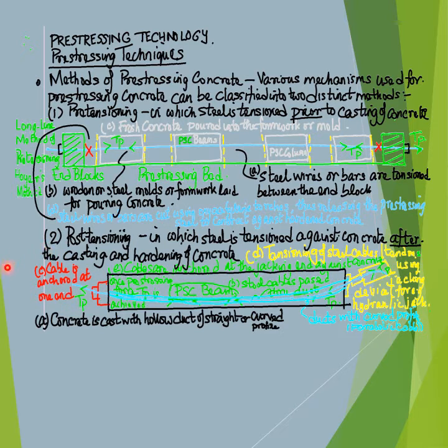In the step C, that is the third step, the steel cable that is passed through the hollow duct in the thus cast pre-stressed concrete beam specimen is anchored at one end using a generic washer and nut kind of assembly or any other proprietary anchoring mechanism.